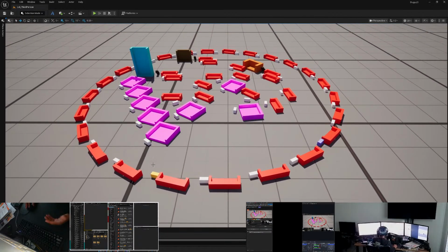There's no texture or image on any of the materials. If there were images, there would be a diffuse map, which is like a graphic that shows the surface of the object. There would be a normal map that shows the bumpiness of the object, or how the light hits the object. There would be a noise map, right? So all of those additional textures on top of a material will add a draw call to the GPU.